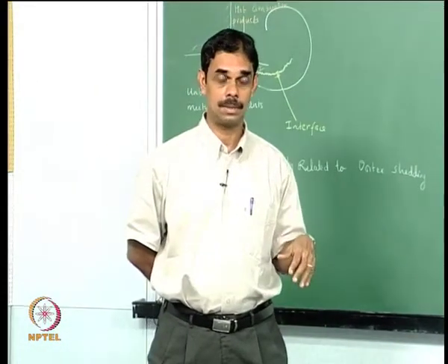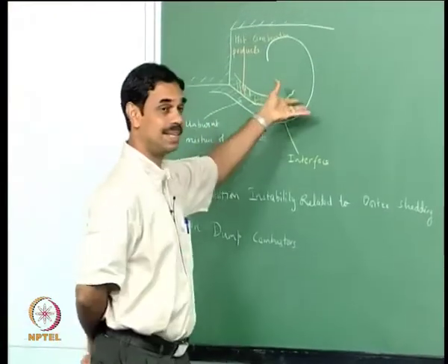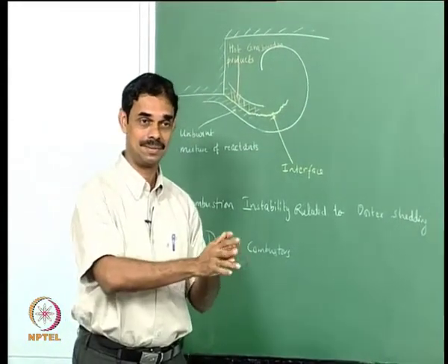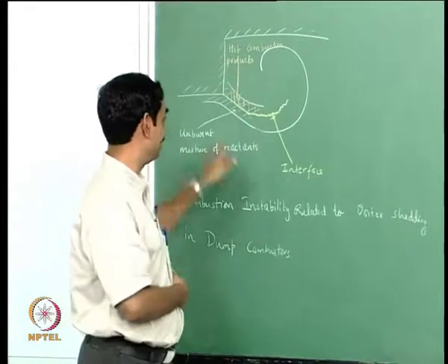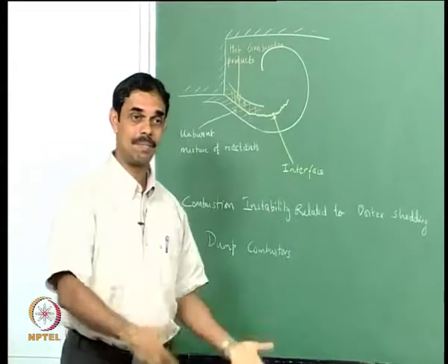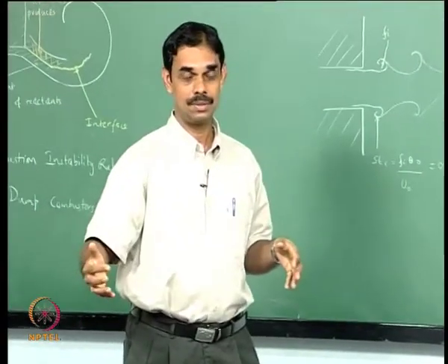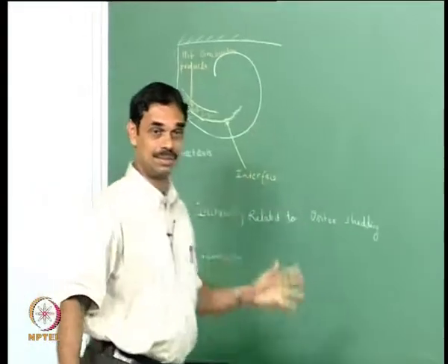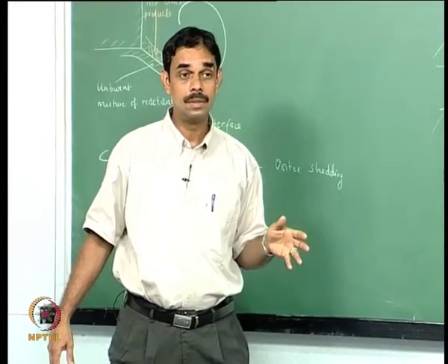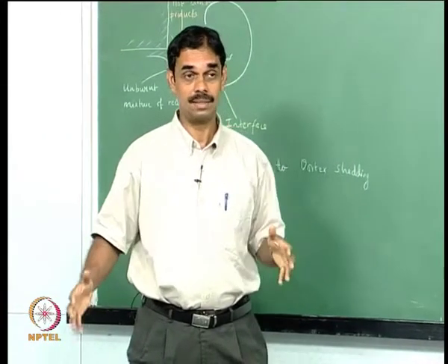So once they break down, why is this periodicity maintained? It comes periodically and then breaks down. So it is periodic to begin with: you start with the large coherent structure and then it breaks down. So you can't get rid of that. You start with the shear layer here and there are vortices and they are merging and all that, and there is only bulk mixing there, and because it takes some time for the small scale mixing, it breaks down after some time. So you can't break this big structure to begin with. Only when it breaks down and we have smaller structures do we have a flame there. In the larger structure we don't have sufficient mixing, so there is no flame and no combustion in there.